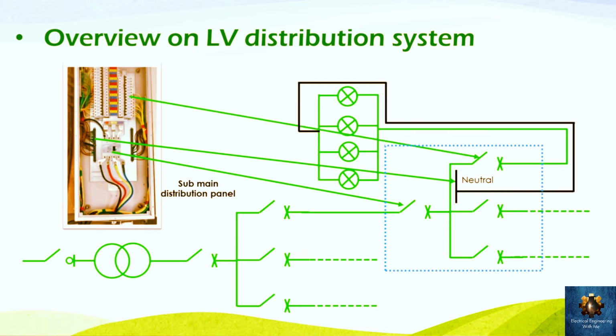So this yellow wire here is connected to the circuit breaker from one side, and it's connected to the electrical loads or to the lamps on the other side. But for the neutral, or this black wire, it's connected directly to the luminaires from the other side.